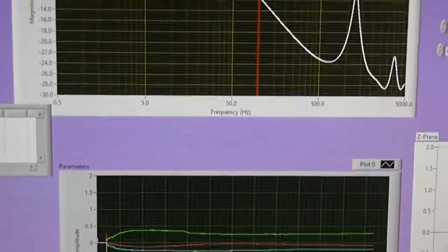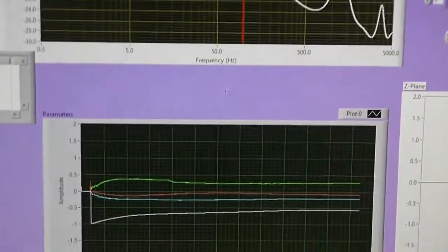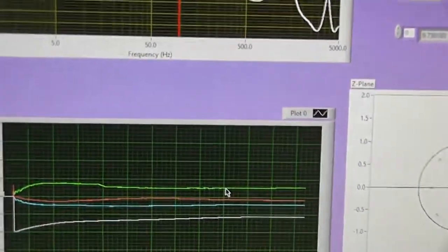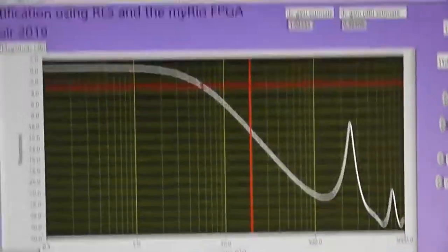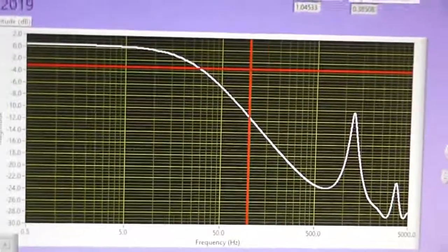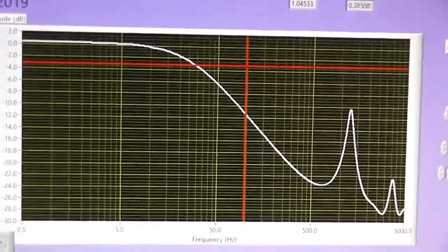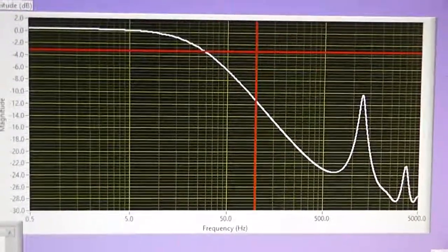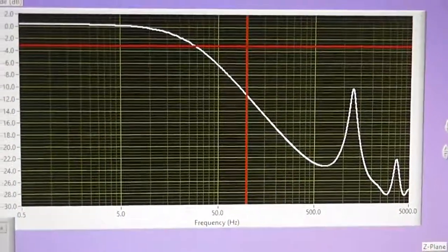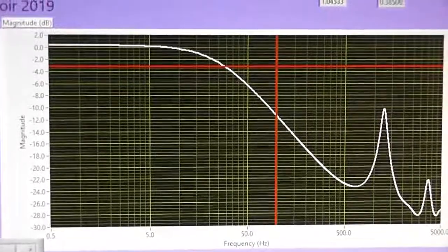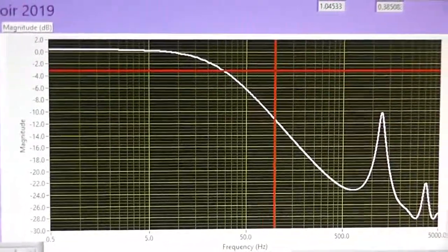So what you have to watch here, as the parameters are converging, is that you operate in a linear region. You don't want to be saturating the motor in any way, so you want to give it running at some reasonable speed well before its limits, and then superimpose a noise term on top of it.